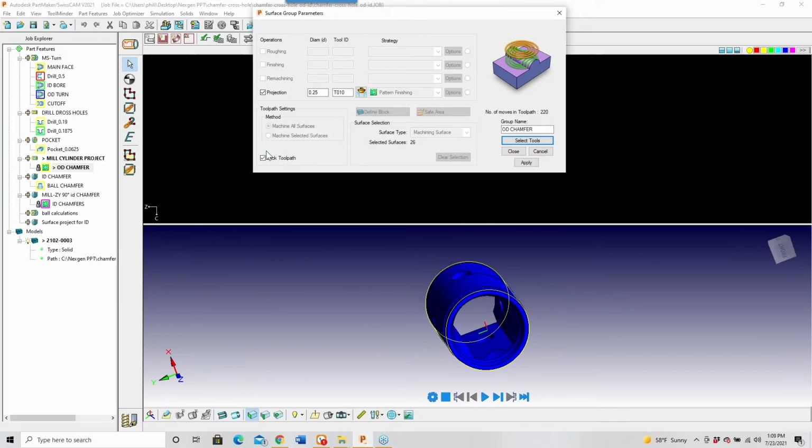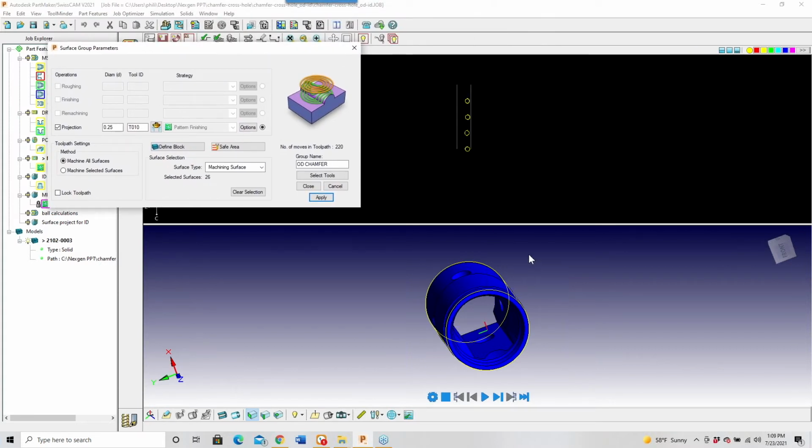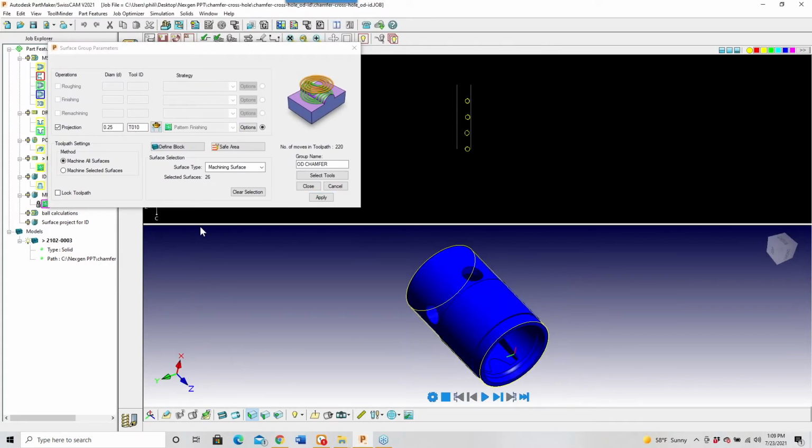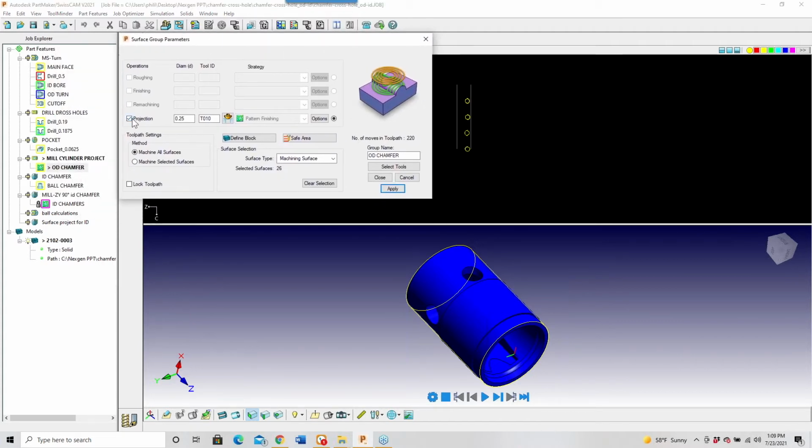Once you've got the tool set, the next thing we need to look at is the projection technique itself. We're going to be taking a 2D profile and projecting it down onto a 3D surface. This technique is going to be using a mill ZY plane, although we could use mill cylinder to get a more accurate projection. So that's what I'm using. I could work with a mill ZY plane because surfacing allows the tool to rise and fall on the edge of the part as it transitions through the curvature of this large surface. Mill cylinder, though, just gives you a little bit more accuracy, so that's what we're using here.